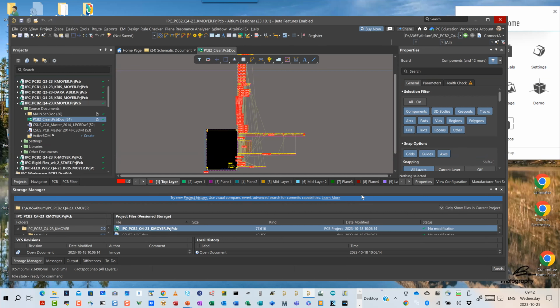Some parts are not, such as mechanical switches. There's ultrasonic washing, where the board is submerged in a tank, kind of like for cleaning jewelry, where there's an ultrasonic vibration that causes the fluid to flow under the parts and so on. You can do solvent-based or water-based cleaning and so on. And that is actually a discussion to have with your assembler, because the honest answer is there's no one right way. It's going to depend on the type of parts you have on your board.